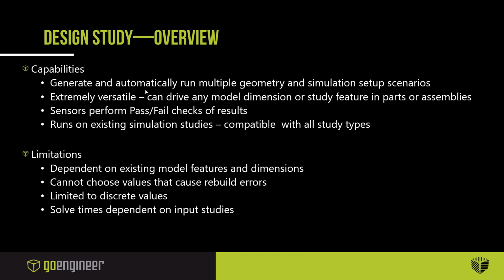And finally, because it runs on regular simulation studies in the back end, solve times are largely dependent on your input studies. So if you are running multiple iterations of a linear static study that takes half an hour to solve, well, a design study is not going to drastically reduce that like a miracle. It's still going to take however long it takes.